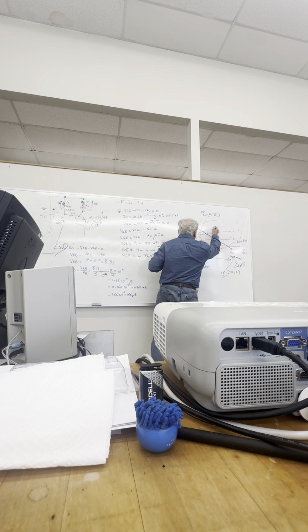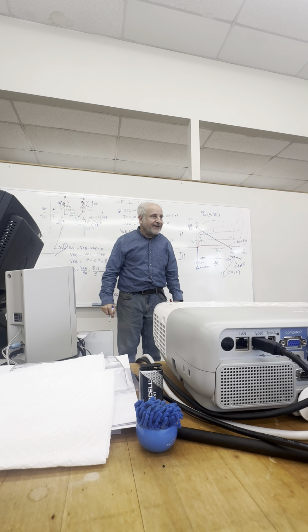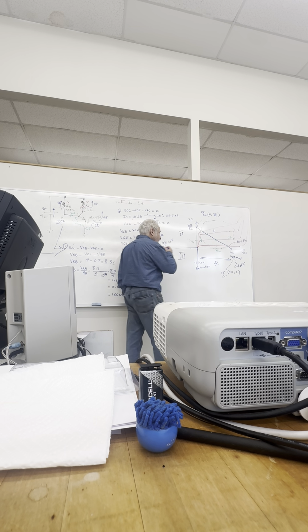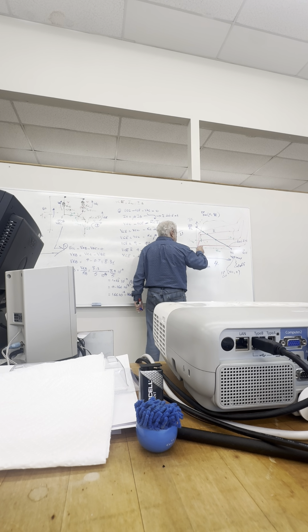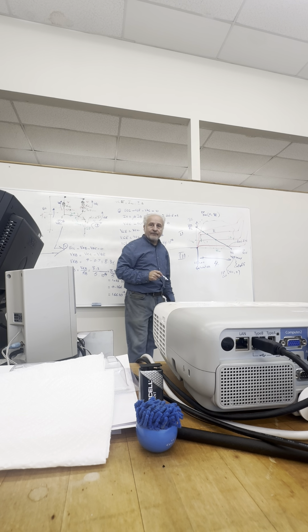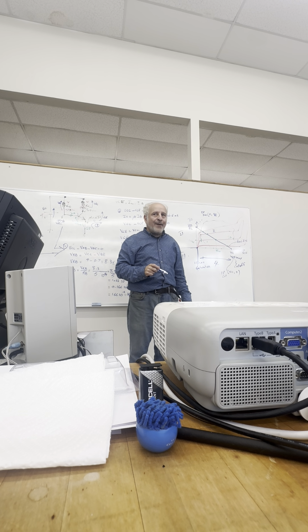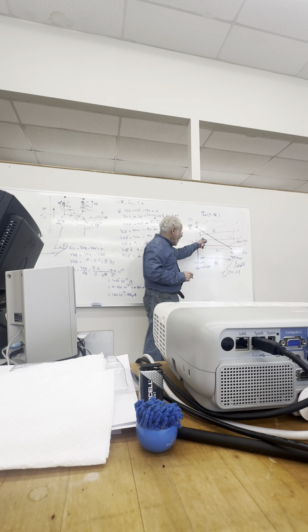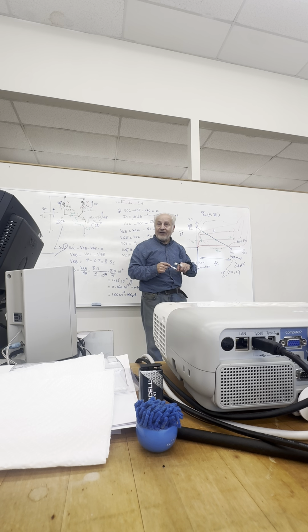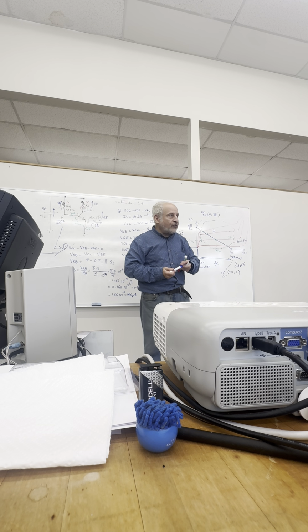This is quadrant 1, 2, 3, and 4. So I don't confuse you. Right? So the ones we're interested in, typically, is this and this. Part 1 of your lab was quadrant 3. Was VBE against IB. Does that make sense? Quadrant 1 is usually VCE versus IC. Once you know these two, you're good to go.